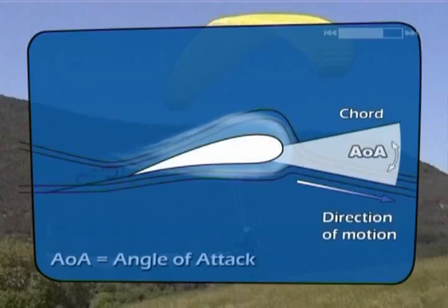The angle of attack can be increased by applying the brakes evenly. This causes a corresponding decrease in airspeed. The greater the angle of attack, the more lift is produced. However, more drag is also produced. If too much brake is applied, then the smooth airflow over the profile cannot be maintained, and the airflow breaks away from the top surface. This is known as a stall.